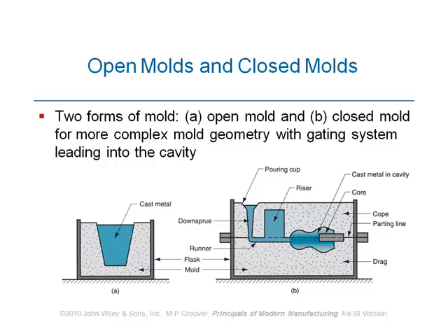Then what happens if the material in the cavity is cooled down to room temperature and it freezes? What happens then? What we get is a shrunk part which is different in geometry than the cavity. It will have a smaller size compared to the cavity which is made in order to make it. Does this sound right? Okay.